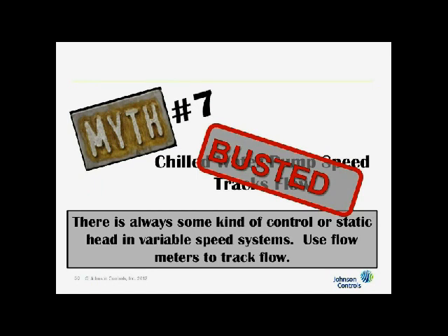And there's a derivative to that myth: if speed doesn't track flow and flow doesn't track load, then speed doesn't track load. And you really need to use flow times delta T to calculate load. That means you really can't avoid flow meters if you want to optimize your plant. And remember, the whole seminar is about how to design the plant for the best efficiency. You need flow meters, and you need good flow meters that can measure well and stay in calibration.